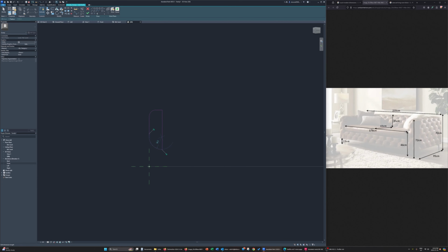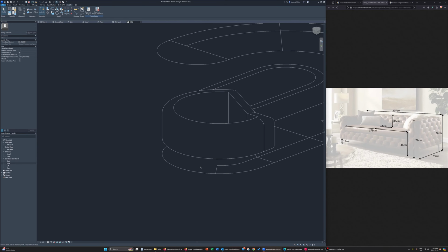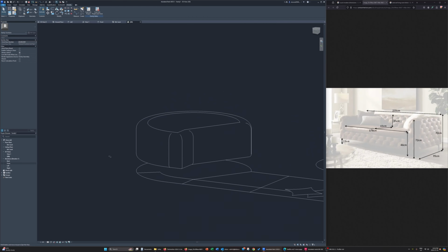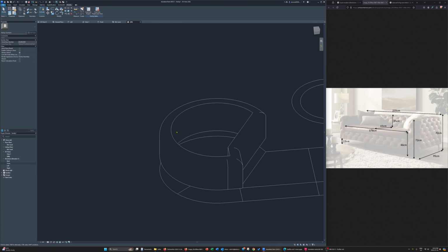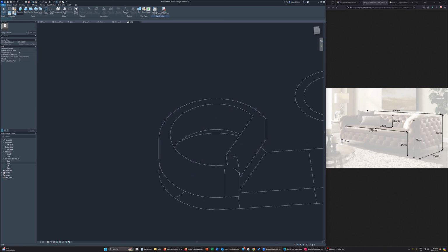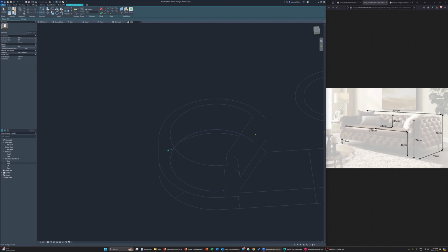And I might do a little bit less here. I'm going to do 25. So we have some round edges more on the top, less at the bottom. And we can kind of see where this is coming. So once again, fairly simple in this way. But once I create this component, we can kind of see I've created my first set of component. So now this is obviously very great, but what I need to do is I need to finalize the middle part. So for that middle part, I'm going to set my work plane to be specifically this plane, and I'm going to make an extrusion, and I'm going to select this path.